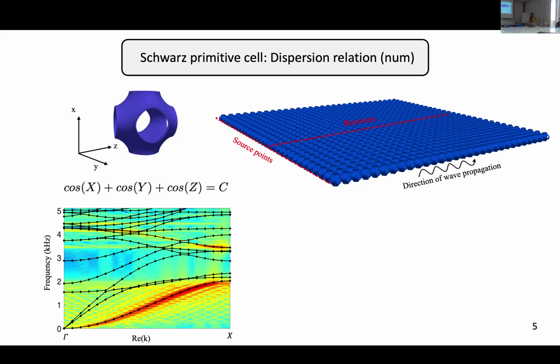And then, along the direction of propagation, I measure equidistantly the displacement, applying the 2D FFT method, and from this data I get what is shown here in the colored background. And you see that now it's clear. Now we see that there are 2 modes, the orange modes, that are propagating. They fit perfectly with what COMSOL had found for us. And interestingly, you see in this range, there is no mode. Just look into the color. There is nothing orange in this range. That means that there is a band gap for the out of plane mode. But we can also verify this with other types of investigations.